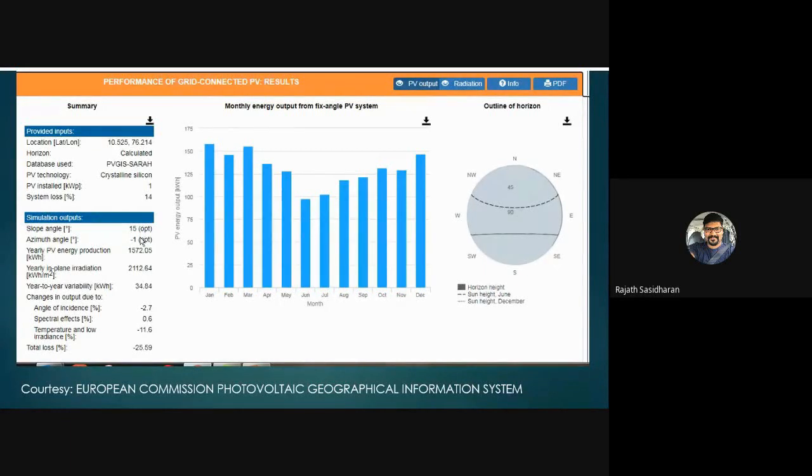And if you build such a system, tentatively it will give 1,572 units of electricity. If your house is having, say, 175 or 250 units for 2 months, then ideally you are consuming, say, 1,500 units of electricity every year. And if you're going for a grid connected plant, then you need a 1 kilowatt system so that you don't have to pay any more bills to the grid. Or basically whatever you consumed from the grid is basically what you produced. Please remember, in such systems, if the grid is failed, then basically you will not be able to export any energy. So that's a complete downtime and waste of energy in such situations.